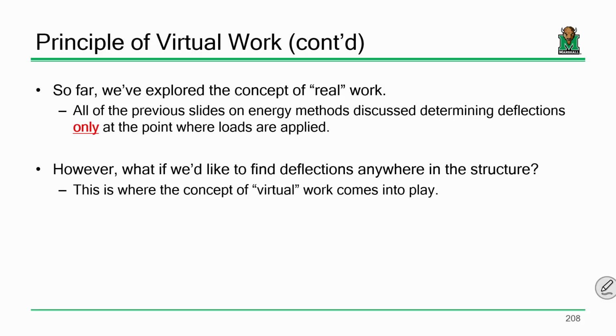What if I don't care about the displacement right here? What if I want the displacement right there? Then it becomes a problem. Because this concept of energies equaling one another, the math I just wrote only corresponds to the point of application. So that works if I only care about determining deflections where the loads are applied. But that's not always the case. I can think of any number of scenarios where you have a load applied, but you care about the response somewhere else. That happens all the time.